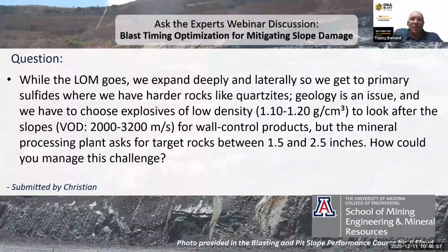I will add that this challenge is to a certain extent certainly manageable if you consider that the fragmentation is linked to the powder factor and the damage to the slope is linked to the charge per delay. But generally, because the mines use a large hole, we have a significant charge per delay, and we don't know how to deal with that. Just because for production you need big holes and big pattern.